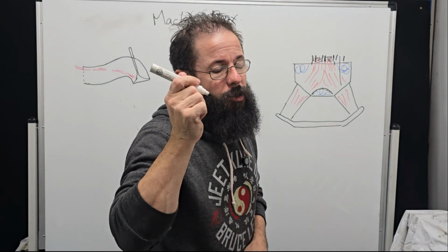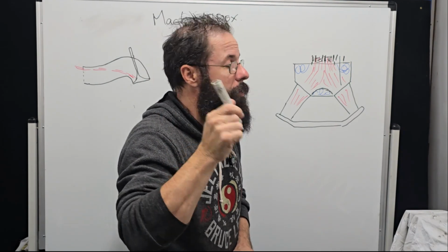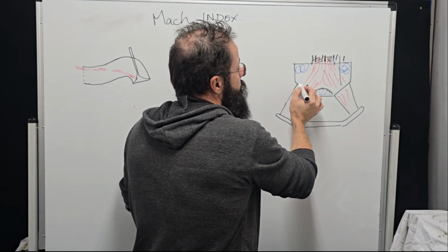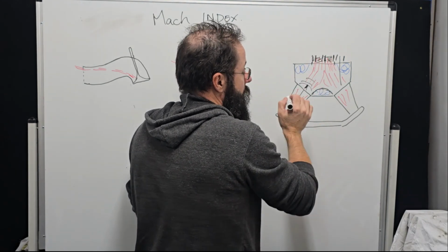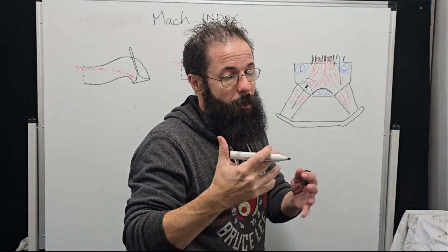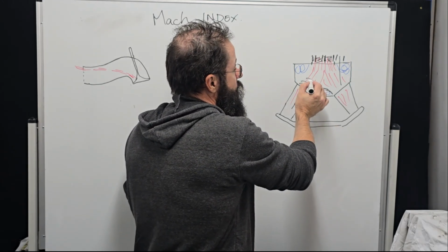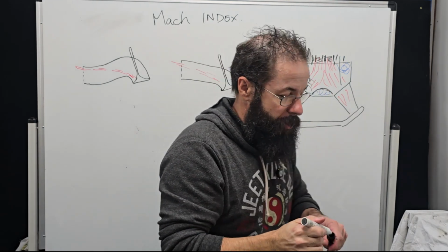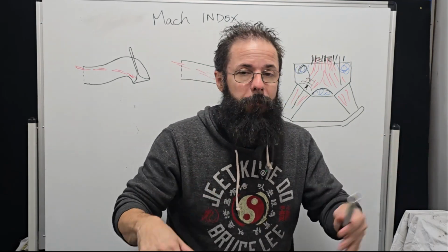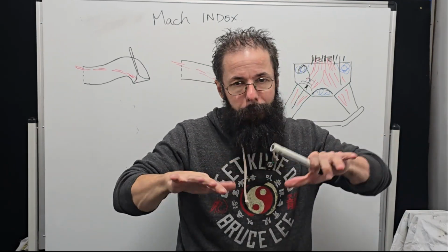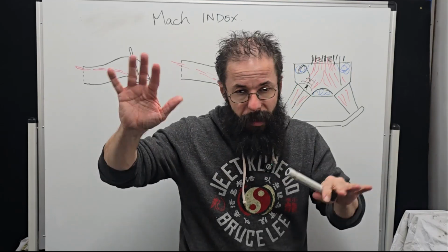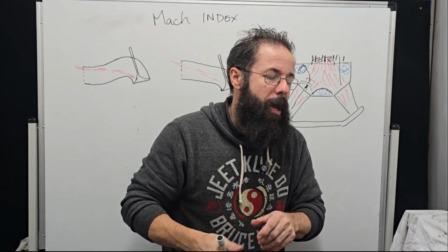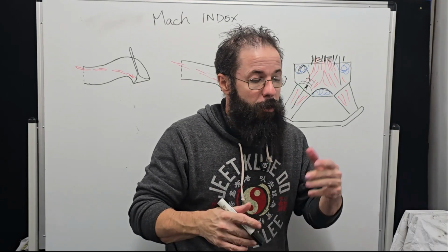And again, if you haven't seen it, check out Darren's video, because he broke this down really, really well. So as these pressure waves come back up, that pressure wave is going to cancel out our booster signal and create all sorts of problems. It's a high pressure, so it wants to fill in. So these dead areas, I've gone to the point of filling them in before, I've even fully bogged up manifolds and shaped the hell out of them. They'll get really, really good in a narrow area and really, really bad in other areas. So you've got to be really careful.